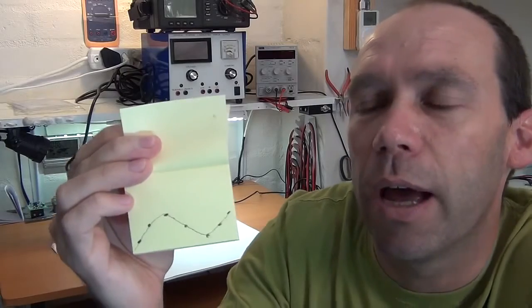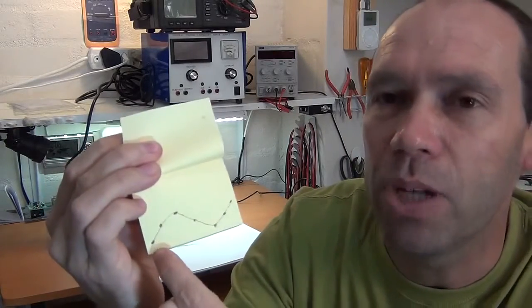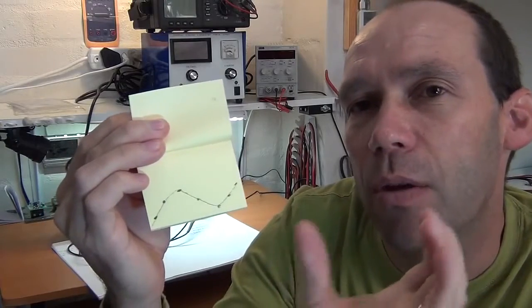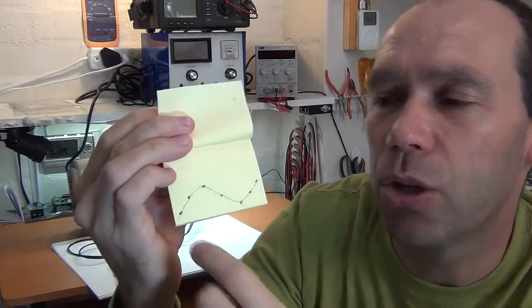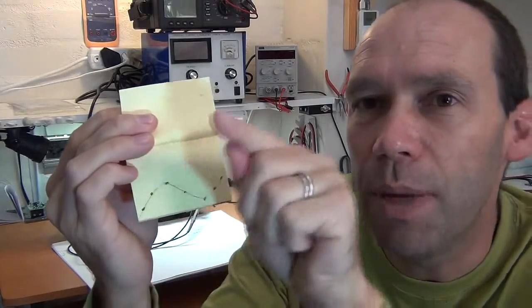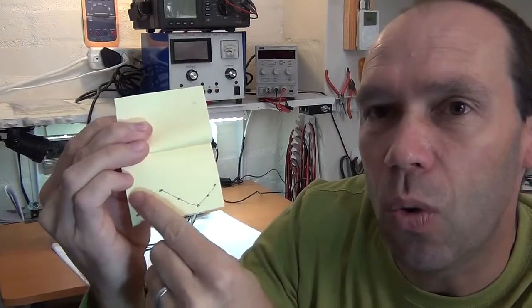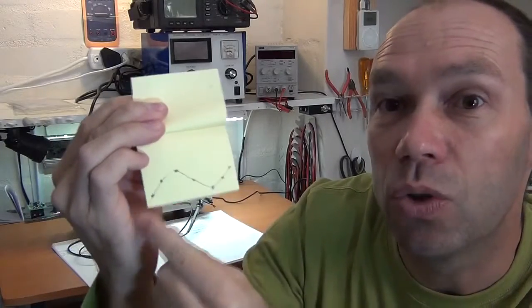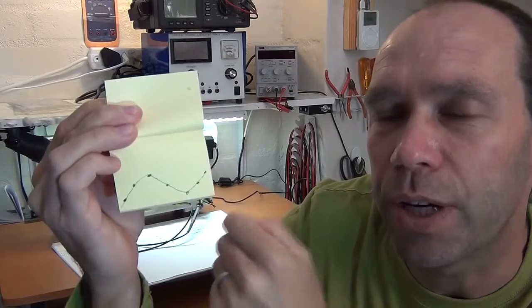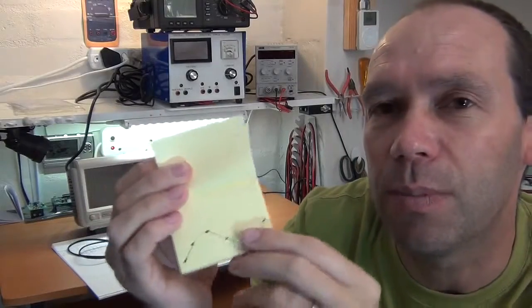And in essence, that's exactly how the old analog oscilloscopes work. They have a measurement and they use those old CRT tubes, cathode ray tubes, and it would alter the beam, or the trace as it's called, as it got a signal. And because of your persistence of vision, your eye, it would actually draw a trace and join the dots, or join the individual measurements, across the screen. And that's in essence how the original oscilloscopes worked. Although it's obviously different today with digital ones. They just have the signal and they obviously plot it on a digital display.